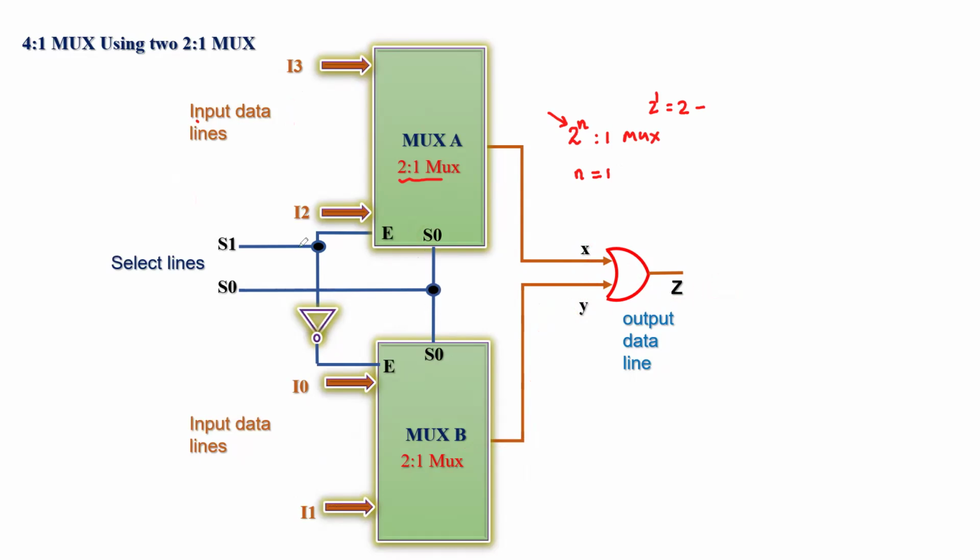That is the digital Boolean equation. Having said that, we have got an extra pin that is called the enable pin, indicated by letter E. This enable pin is basically used to switch on the multiplexer chip, depending on what logic you apply to it. When it receives logic 1, the multiplexer chip is enabled, or in other words, switched on.